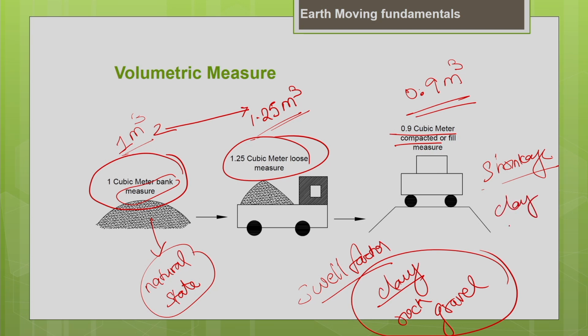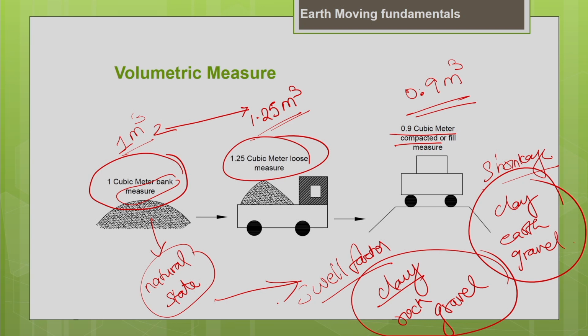Clay has its own shrinkage, as I told you. The earth, the gravel, everything has its own shrinking ability. So you have to do some geotechnical investigations to study the swell factor or the clay shrinkage factor, or you can take it from the literature. There is a lot of information available for different types of material related to swell factor and shrinkage factor. You can make use of those values for your estimations.